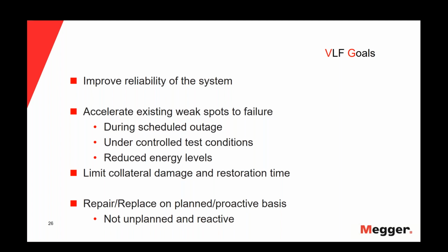When the cable fails during service, I will have a higher amount of energy, and for that reason I could have collateral damage. When the cable fails during a VLF test, the energy is smaller, and for that reason I have limited collateral damage. The other goal is that we will repair and replace on a planned and proactive basis, not on an unplanned and reactive one.